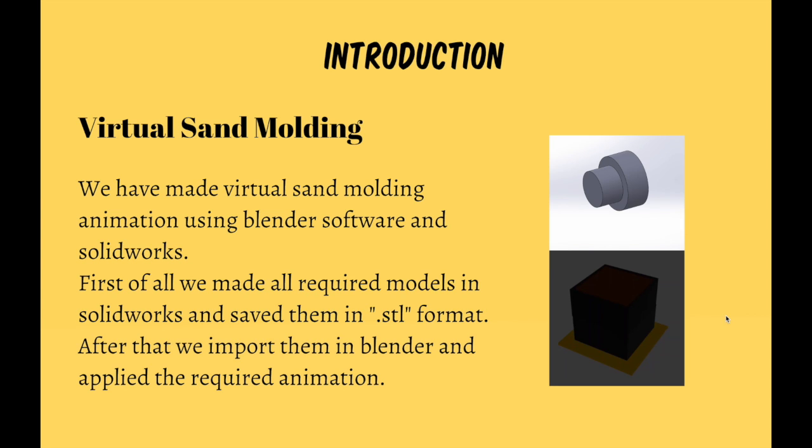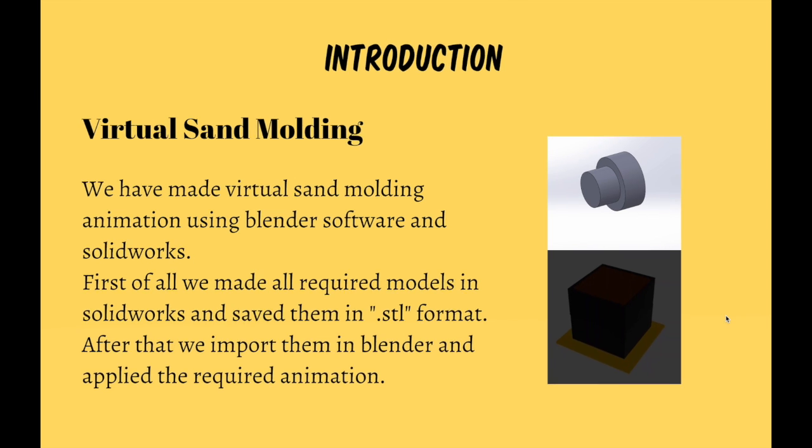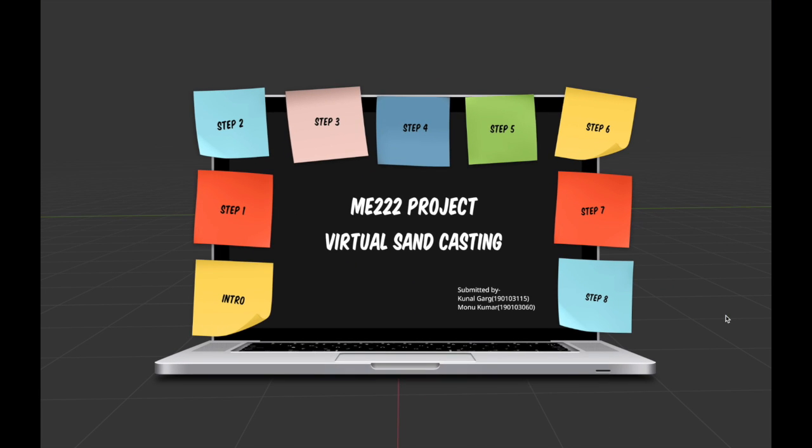Introduction. Virtual sand molding. This animation we have made using Blender software and SolidWorks. First of all, we made all the required models in SolidWorks and saved them in .stl format. After that, we import them in Blender and applied the required animation. Now moving on to step 1.